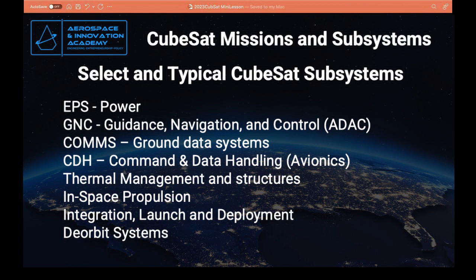But very quickly, the components you want to think about as you look at your comm system are an antenna and a transceiver, which can both send and receive a signal, and then of course, you may need an amplifier. These CubeSats have very small antennas. And for instance, the satellites we work with are either simplex or duplex radios. A simplex radio means it is basically receive only, and a duplex radio can transmit and receive.